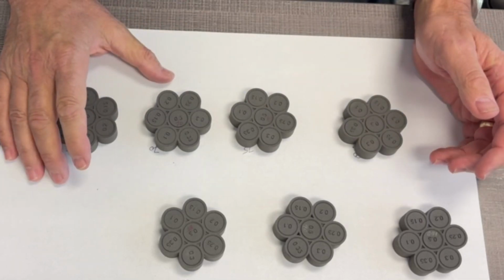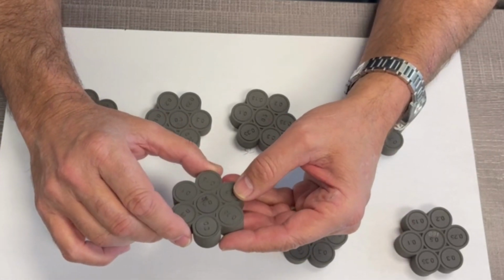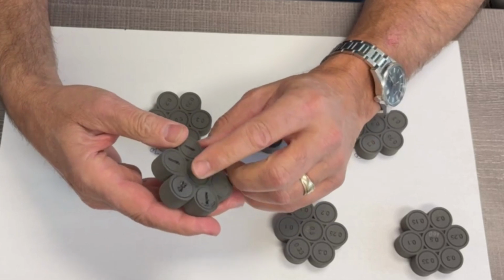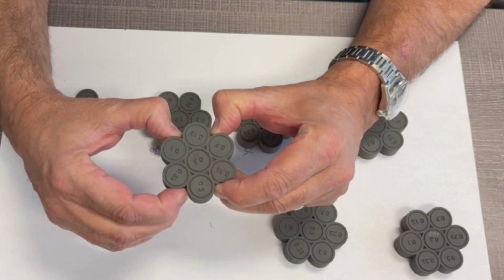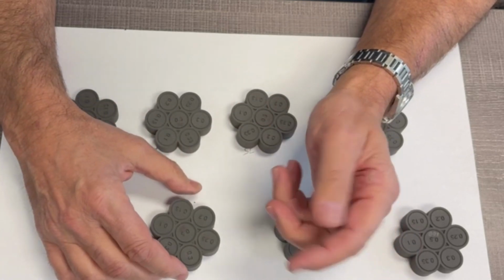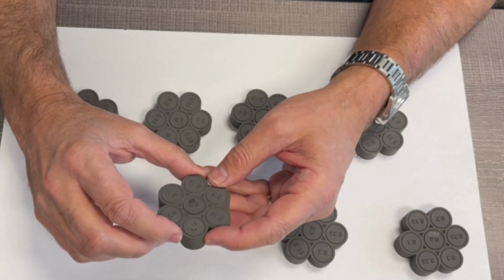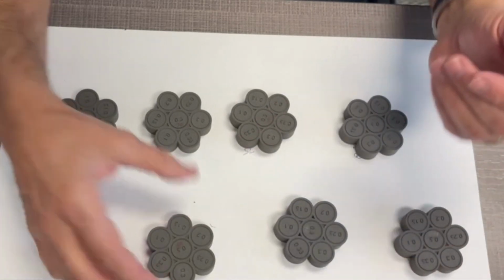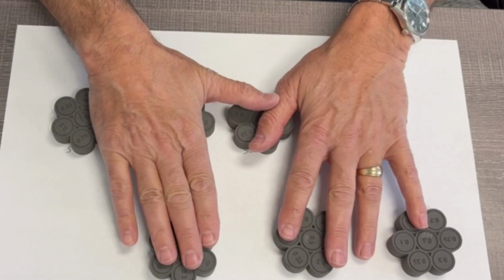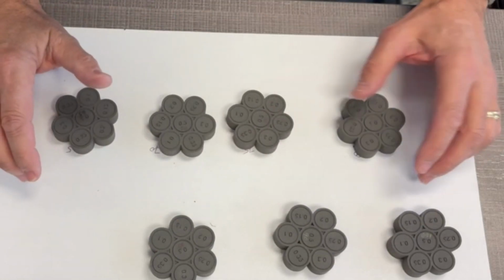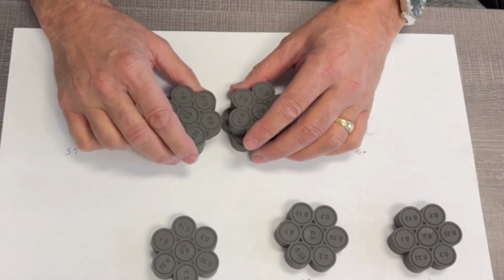So in discussion with Thomas, he felt like I shouldn't go below 0.85. He felt like, I met the 0.3, although I had to really crank hard to get that to break loose, because he was afraid that the mechanical properties and the ability to do thin walls would be impacted if I went lower. And of course, I'm a curious person, and I wanted to actually test to see if that would be correct. So what I decided to do, now that I kind of know where I can operate and still make good parts, was lower the laser energy density during the fill and outline phases.